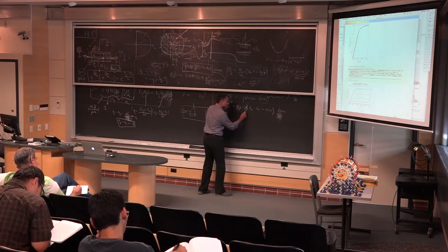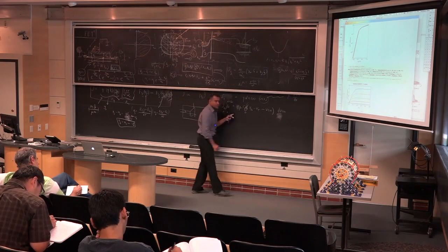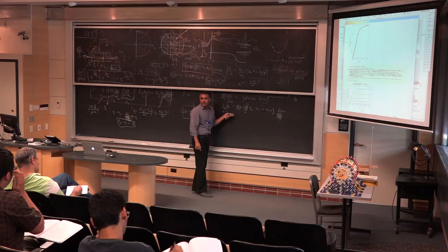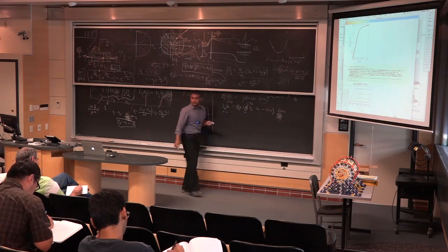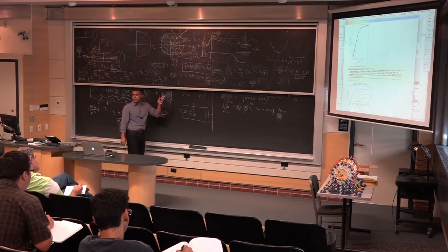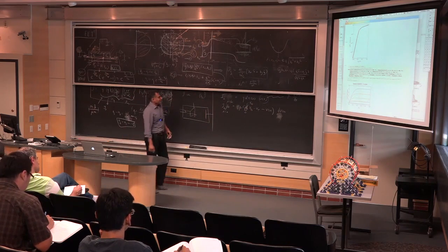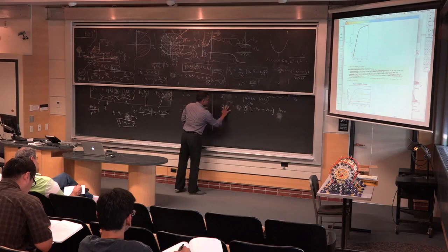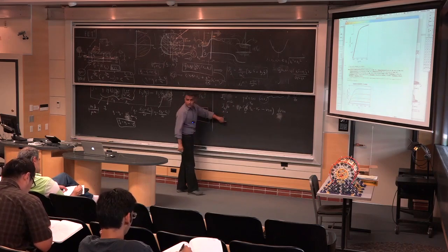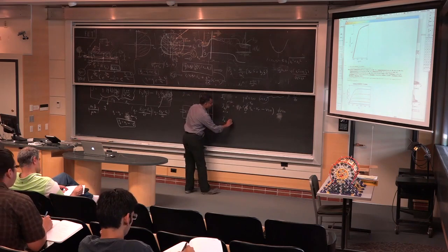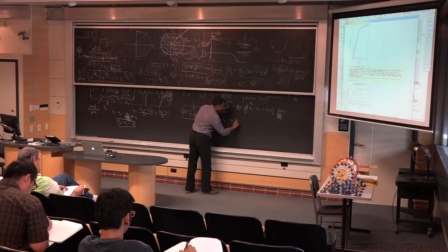And at x equal to 0, my potential, the source potential, is 0, right? And at x equal to L, my V of x is VDS. Makes sense, right? Do you see what I mean? The beauty of this is it's the simplest integral. You just get ID times L. You take L to the right side, and you get mu times gate capacitance times W over L.